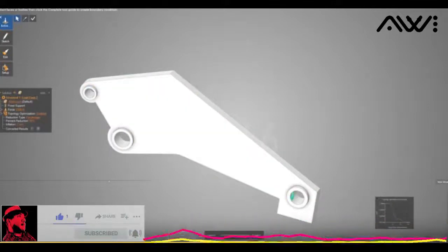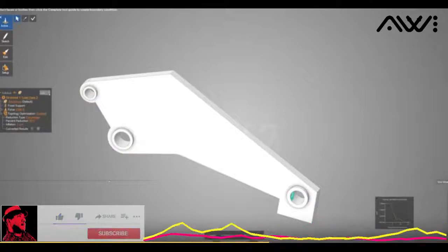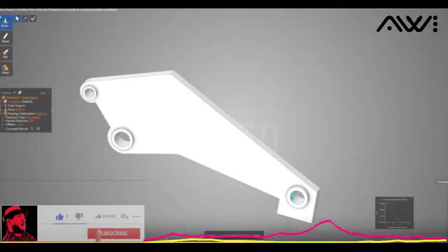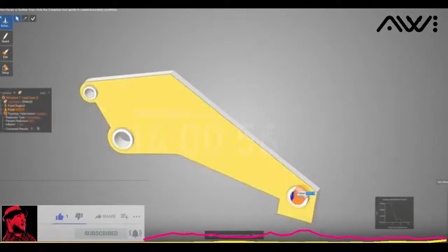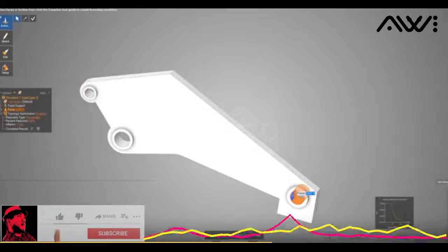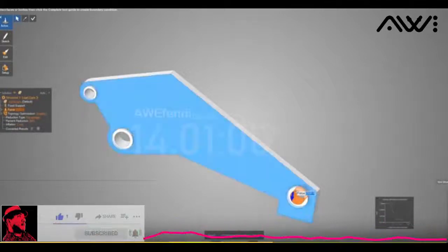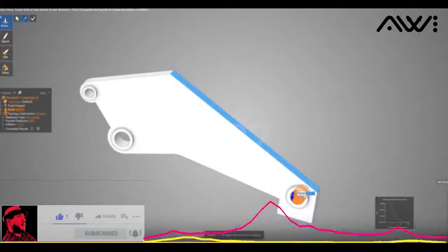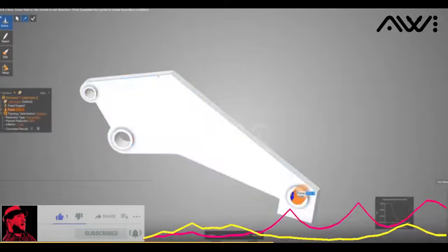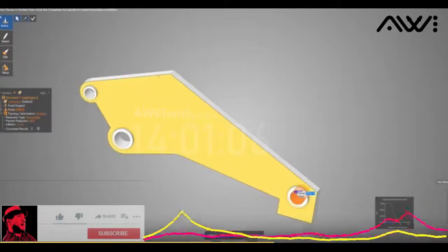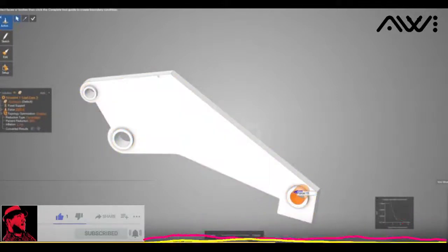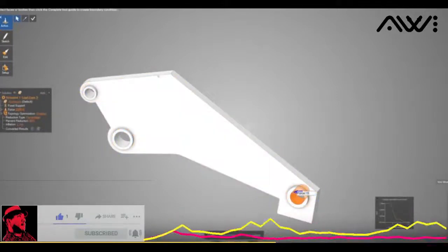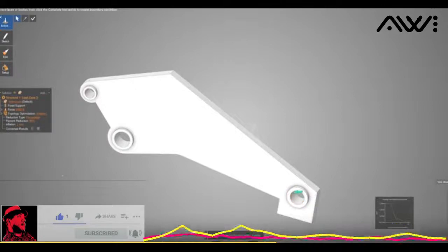Well, where else would we see a different force? I'm going to come back, another load case 3. Let's edit this one, that's 2,500, edit, and the hotkey to move this around is Alt, so pick up faces, edges to change the direction. So maybe a force is coming in at that kind of angle, and let's make this one now 1,500. Now we have a new load case right there. So now that one's 1,500.